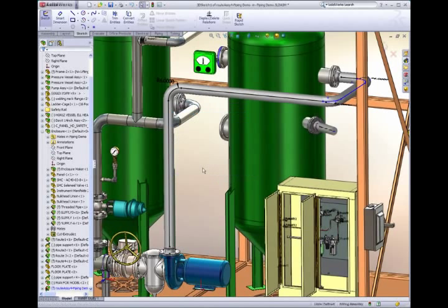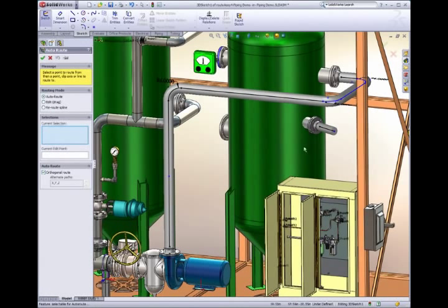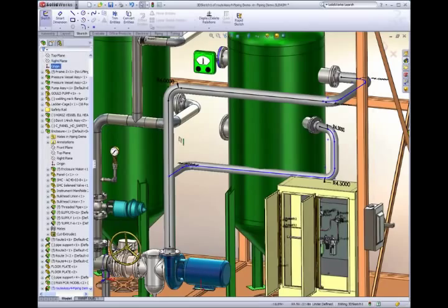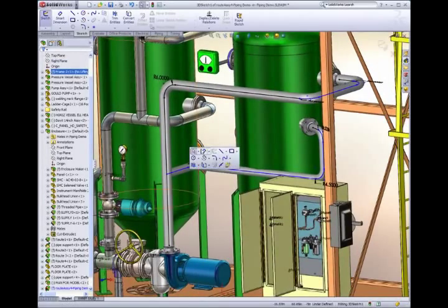Here, I'll connect a smaller flange to the piping spool. I can specify the intersection point by simply choosing a location in the existing pipe run. SOLIDWORKS can automatically connect the two locations for me, and all I need to do is modify the size and maintain desired clearances. And I can either drag the pipe into place or use dimensions to size it appropriately.